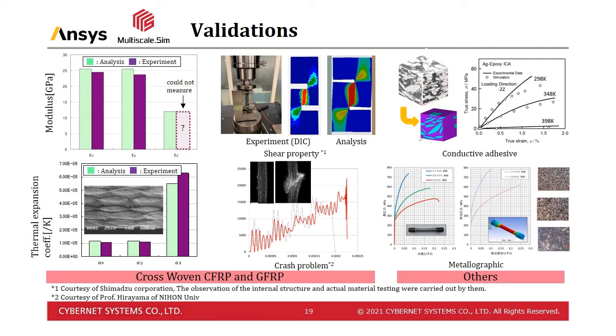We created the model for the microstructure based on the image observed by X-ray CT, since the shape of the silver filler is not simple. This image processing cannot be performed by our tool. We use another software called Simpleware sold by Synopsys. We compared the inelastic stress-strain characteristics of the composite state. The last one is an example of predicting the elastoplastic properties of metallic materials.